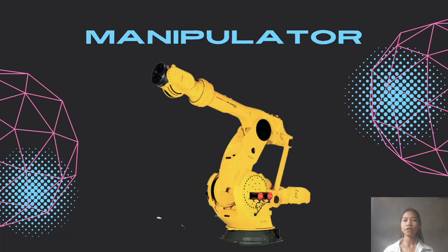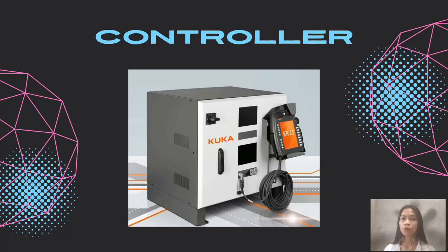The arm and body joints of the manipulator are used to position the end effector, and the wrist joints of the manipulator are used to orient the end effector. The robot controller is a computer composed of hardware and software linked to the robot and essentially functions as its brain. Controllers have all of the characteristics associated with computers and contain sophisticated decision making and data storage capabilities.